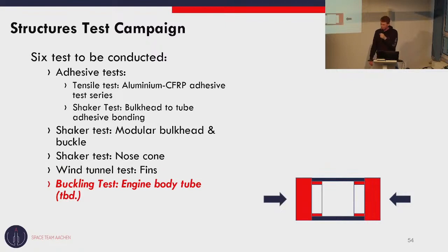Lastly, we are considering a buckling test for the longest body tube, which is the engine tube. However, we're expecting very high safety factors with our finite element analysis, and if the safety factors are exceedingly large, then we will disregard this test to save both resources and workload.